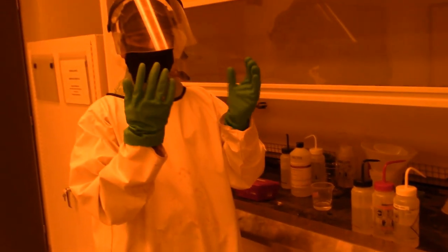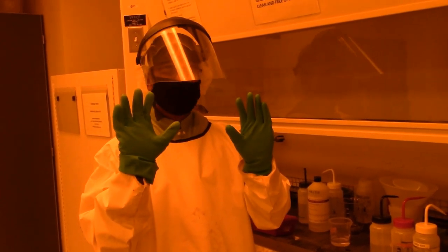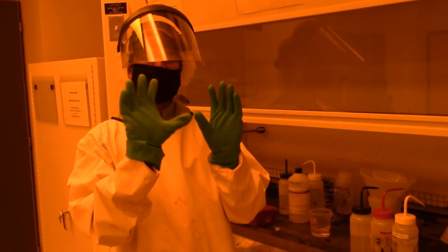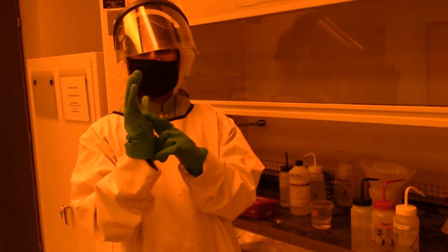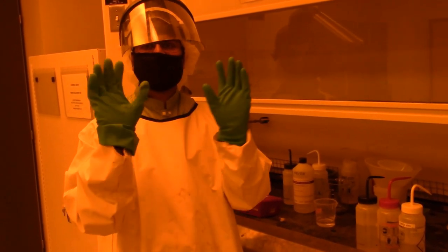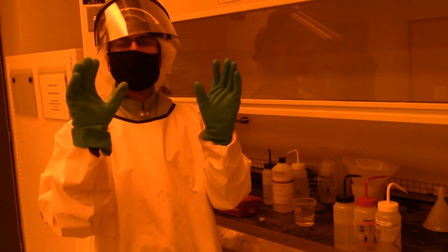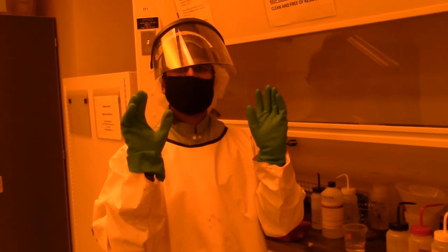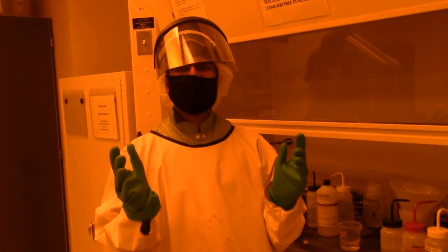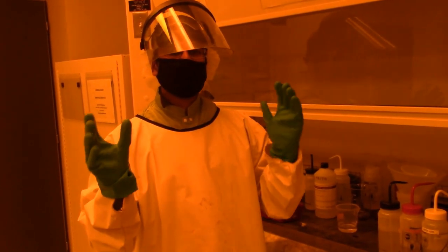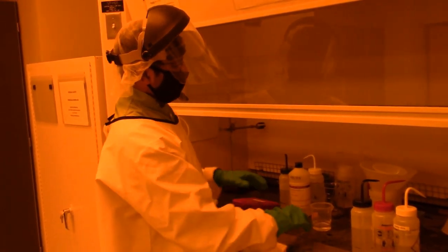Before the etch, make sure to inspect your PPE, especially your gloves, so that there are no wears and tears on the gloves. Any tear can be a potential place where acid can get into your inner glove, which might not give as good protection as it needs, and eventually get onto your skin. So that's not a good thing to want to have.